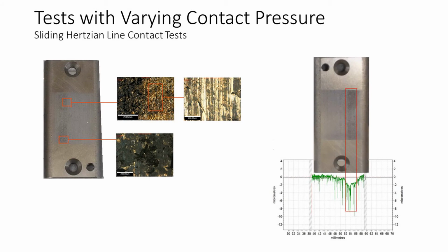With the parallel sample, both reversal positions indicate severe adhesive wear, characterized by deep holes in the surface. The lighter regions outside these areas have cracks in the surface, suggesting mild adhesive wear. There is a clear distinction between the severe band and the areas subjected to mild adhesive wear.